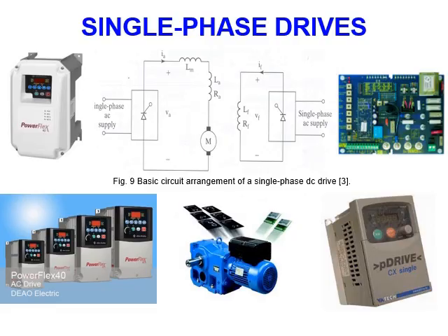Now, after this introduction revision for the DC motor, let's go for our power electronic converters, how we use them to control the motors. As I mentioned, we either control voltage, armature voltage, or field current, or armature current, and this needs to be done by a controlled rectifier. We discussed controlled rectifiers, remember? Different types: we have half bridge, full bridge, half control, full control, and so on. Single phase, three phase.